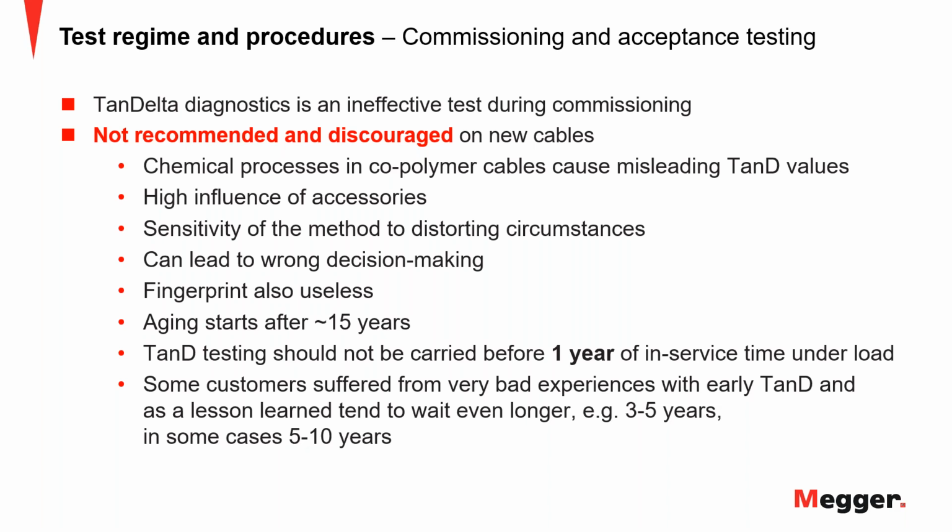And a lot of our customers that we talk to, they don't do anything down that road before maybe 3-5 years. Some even say, no, before 10 years, I'm not worried about tan delta. So keep this in mind. The important test for commissioning is the partial discharge test.